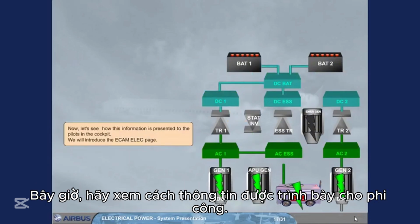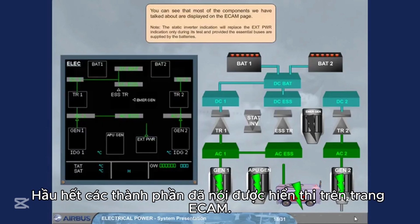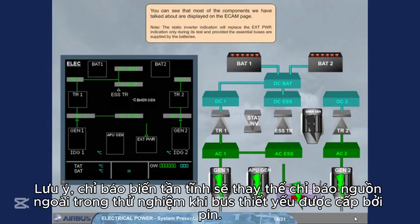Now, let's see how this information is presented to the pilots in the cockpit. We will introduce the ECAM electrical page. You can see that most of the components we have talked about are displayed on the ECAM page. Note, the static inverter indication will replace the external power indication only during its test and provided the essential buses are supplied by the batteries.